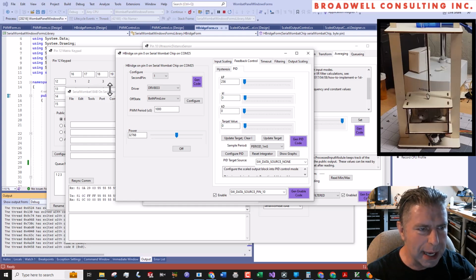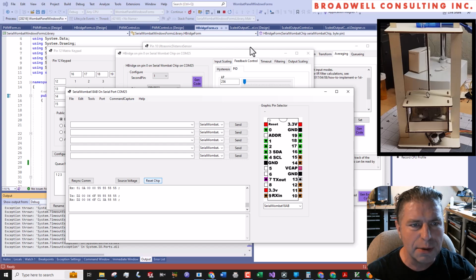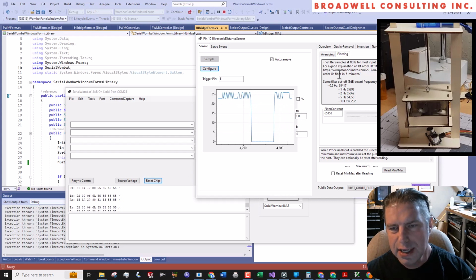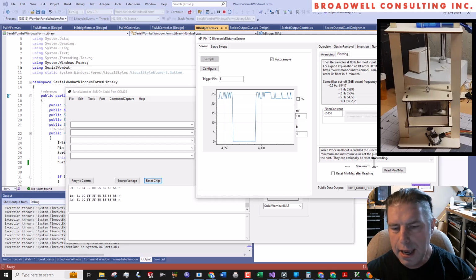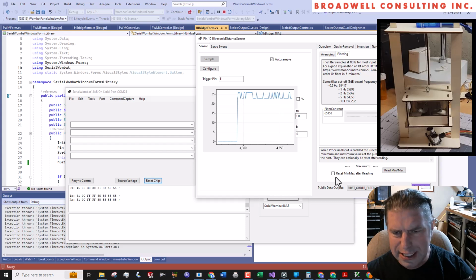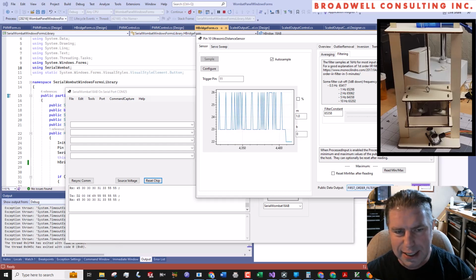I'm going to take the chip back here and run it through a reset. That will clear everything that we got going on. Configure. That gets us back, and okay, we're at about 25 millimeters. This time we're going to skip doing the transform on this thing, and we're just going to operate in millimeters because the hysteresis mode doesn't really need that concept of min-max. Hysteresis is what we're going to do to control it. Some people call that a bang-bang controller. So I'm going to hit this again and get that filtering in place.